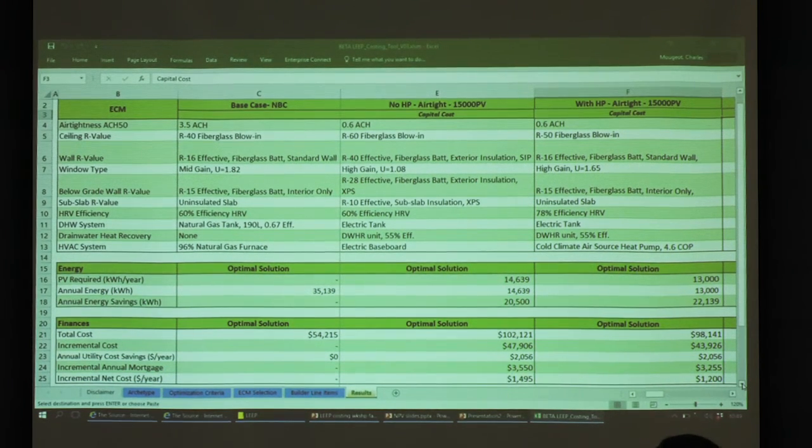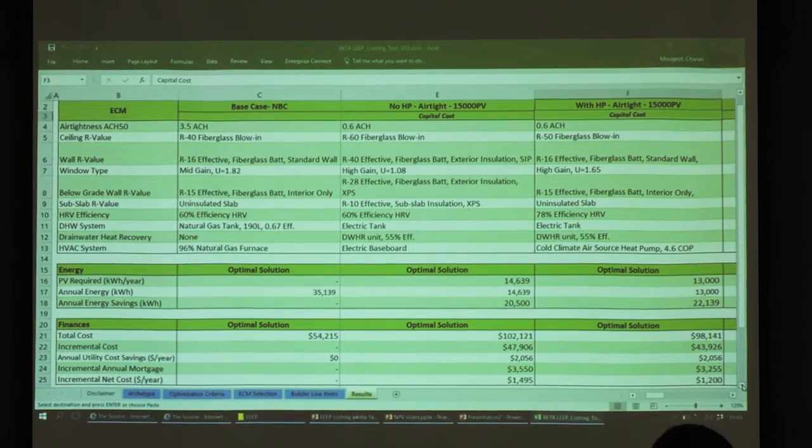So sometimes the spec'd heat pump is the same outside of the house, the coil gets switched and the COP changes. And the impact on the energy model is not necessarily understood when that change is made. It's an economic decision or an availability decision, et cetera. So certainly complexities, because it's one of those interrelated pieces of equipment that relies on the heat pump unit itself, the fan and the coil, all working together to achieve that COP. So yeah, that's really difficult to check.